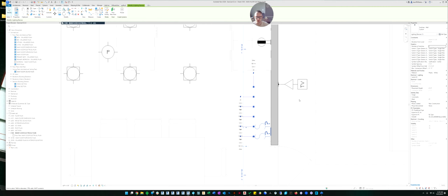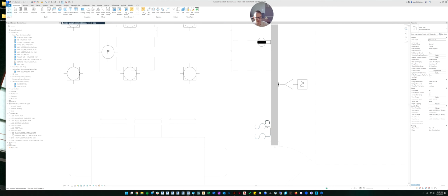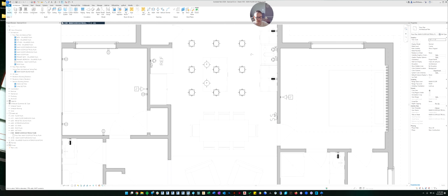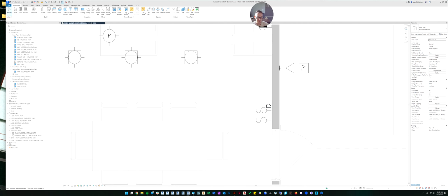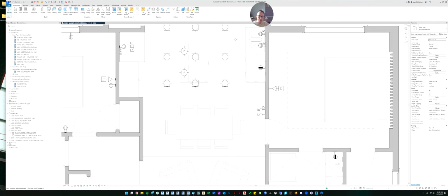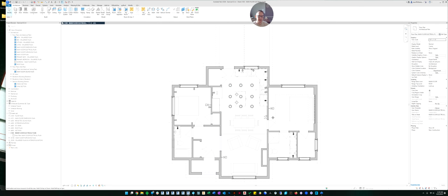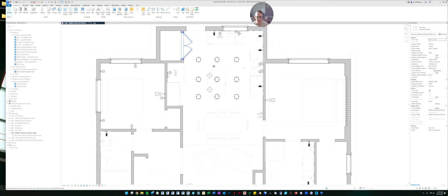Let's go back to our electrical plan. And let's make switch 1 by default a single pole. So let's keep it like that. And switch 2, let's make it a dimmable switch. So you can click this drop down and you can call it a dimmer switch. And then do you see how it adds a little D there to let people know that that's the dimmer switch? So we're going to make the pendant lights dimmable, and the main lights will go on a normal switch. Okay, so there we go. We've got our switches in, and again, you can do that throughout the entire house.